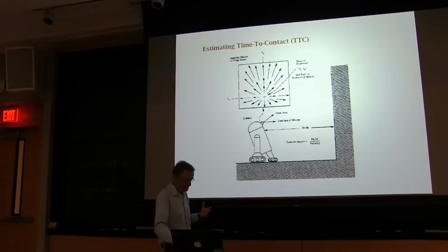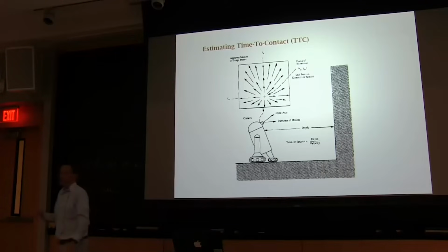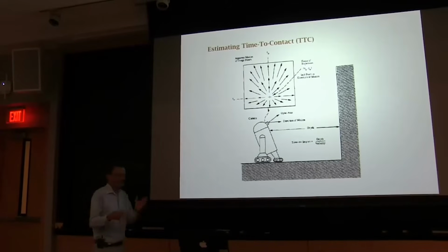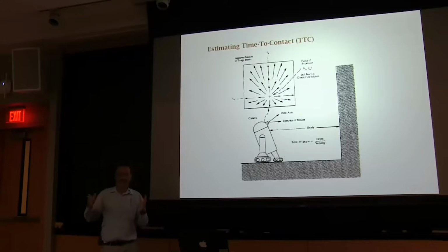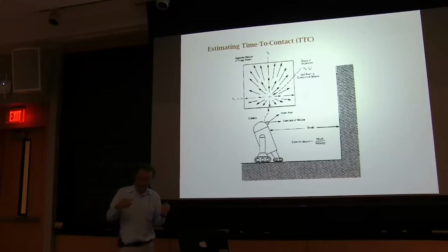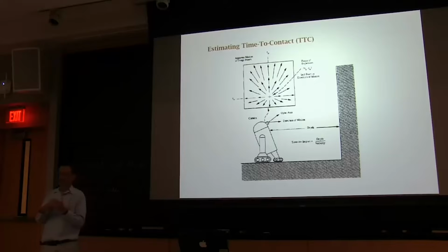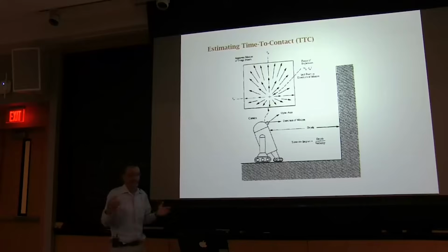there are interesting aspects, like one camera, don't need two. The other one is that for many of the things we do, we need to know things about the camera, like the focal length. And we need to know where the optical axis strikes the image plane. So we've got this array of pixels, but where's the center? Well, you can just divide the number of columns and the number of rows by 2, but that's totally arbitrary. What you really want to know is, if you put the axis through the lens, where does it hit the image plane? And of course, the manufacturer typically tries to make that be exactly the center of your image sensor, but it's always going to be a little bit off.